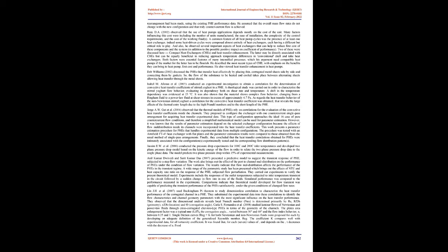They proposed the effect of flow distribution on the thermal performance with varying design factors, i.e., the locations of separators and inlet/outlet, and the aspect ratios of microchannels of the heat exchanger. The observations were made for flow uniformities along the paths of the heat exchanger, and to evaluate the thermal performance of the heat exchanger. It was found that the heat transfer rate of the optimized model was increased by 6.0% compared to that of the base type, and the pressure drop by 0.4%.